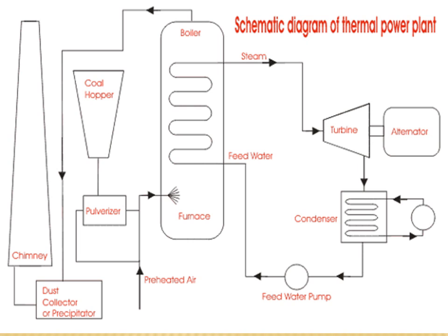The fourth one is the cooling water circuit, which is located in this figure just below the turbine. The quantity of cooling water required to condense the steam is considerably large, and it is taken either from a lake, river or sea. The cooling water is taken from the upper side of the river.